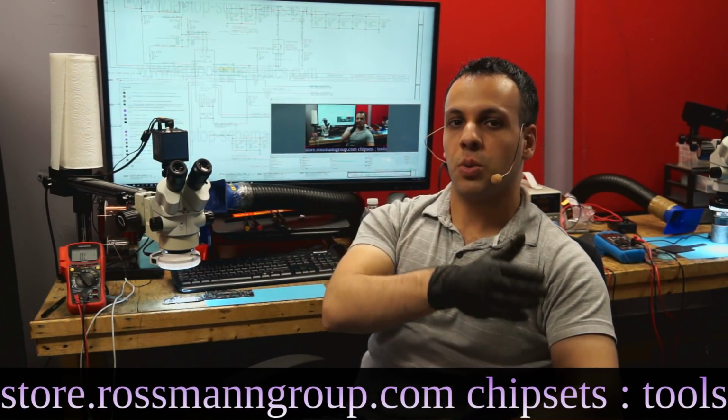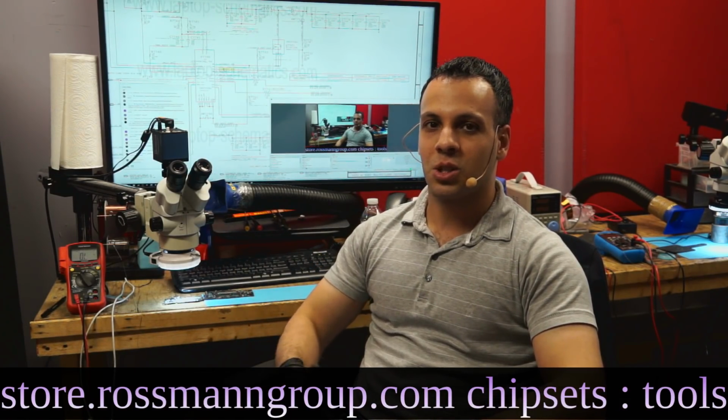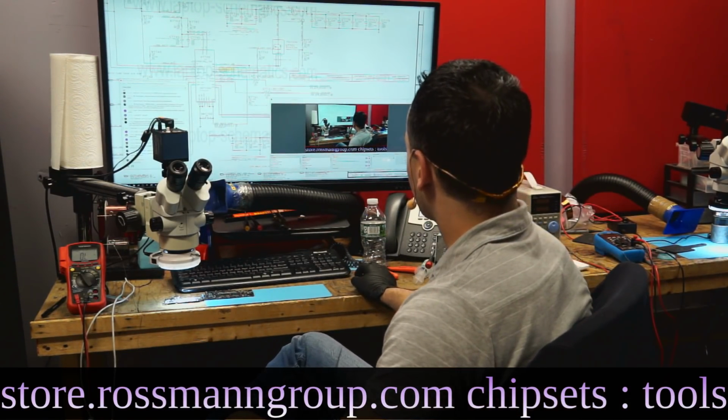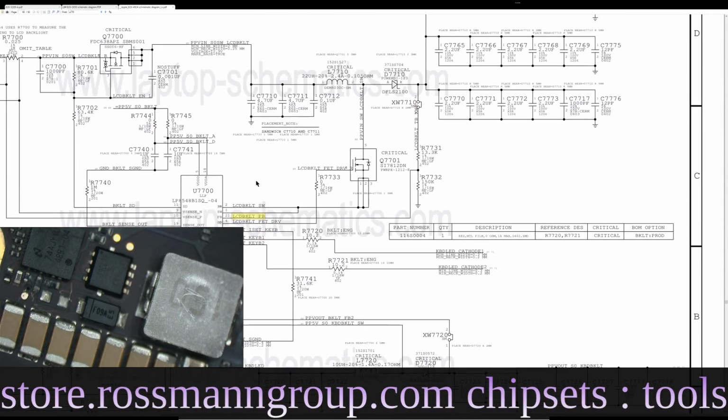The boost circuit that makes 12 volts into a 30 or 40 is not going to do boosting if it can't see what it's creating. What if it's creating 50 or 90 or 1,000 or a million volts and it's destroying something? We can't have that. So the way that we control this is with feedback. So this little feedback line over here is going to go between output and the chip so that the chip can see what it's doing.